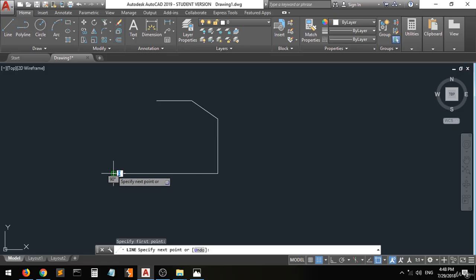So as we said, we will move 0.25 in the vertical direction. And again, you can use whether the coordinate entry, the relative coordinate entry, or the polar entry. Anything you think is easier. So I'll do it in the polar. At 0.25, since it's going in the positive direction, right? Then we'll do it at an angle of 90. And then we have this.